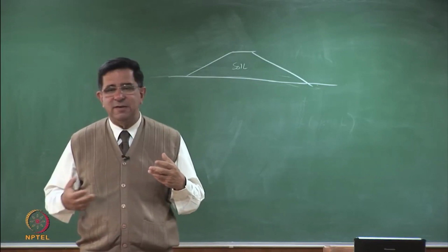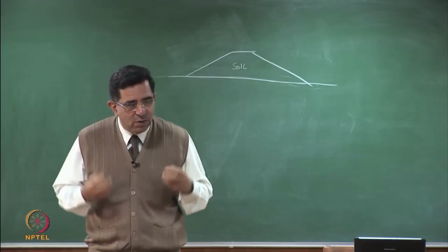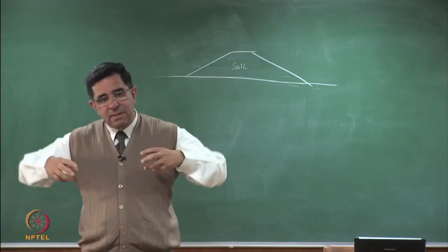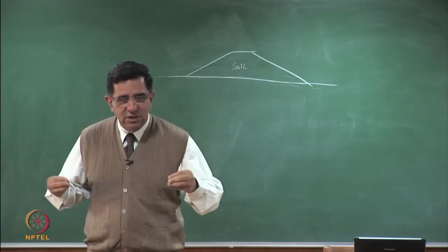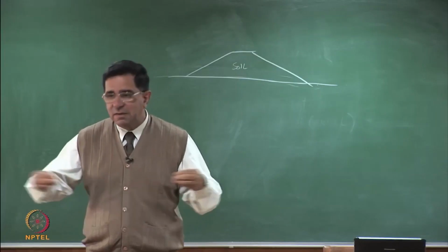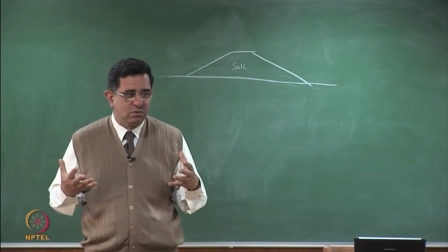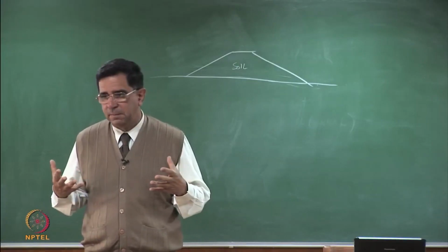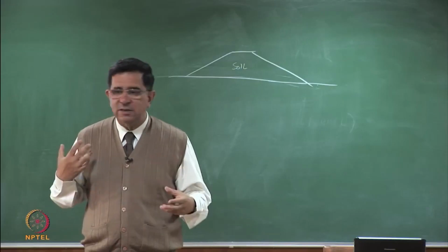It means that it's a mathematical representation. So if you have fibrous material, they might give you some apparent cohesion. Now fibrous would be plastic sheets, small polythene bags, cloth. So you do get values of cohesion intercept. And so you get C dash, phi dash.